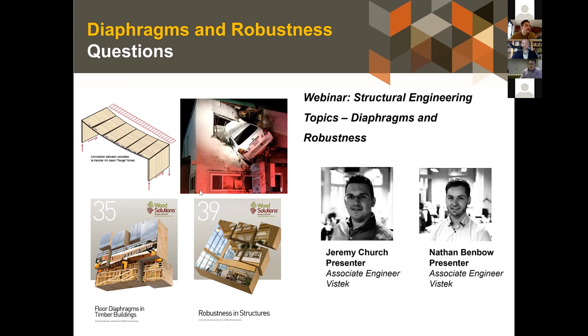The concrete topping. When you're using that for acoustics, can you consider that in the diaphragm design? It would depend on how you're actually connecting that. If you're not using shear connectors in the sense of screws to provide that shear flow transfer and getting some sort of composite action, I would suggest not, unless you can verify that you're going to have direct bearing. But if it's sort of on a membrane, that means that bond is lost, I wouldn't suggest that you use that in combination with your structural assessment of the element.